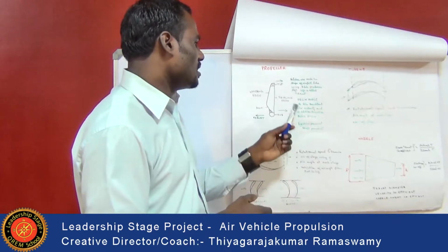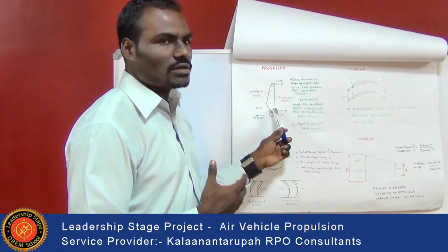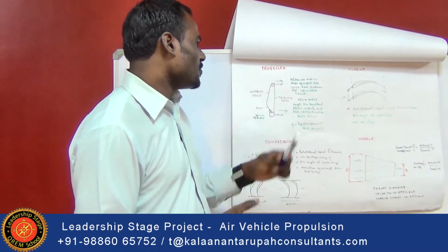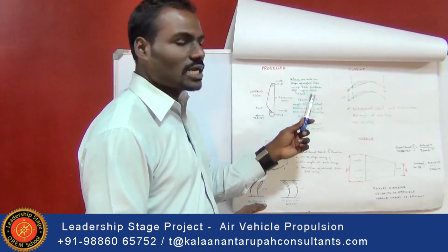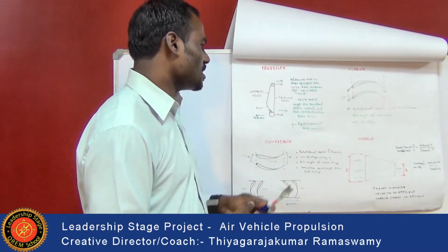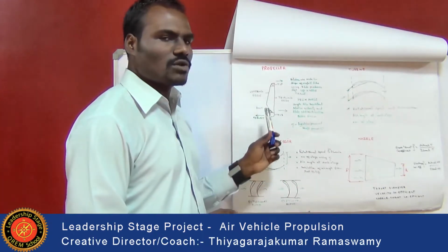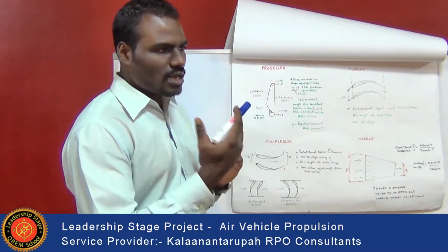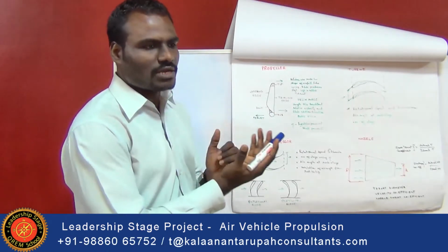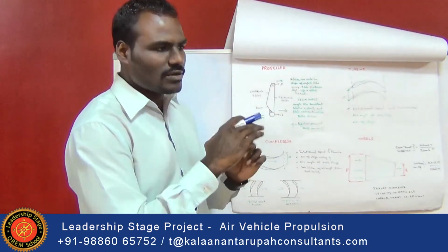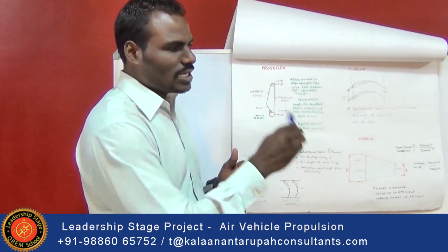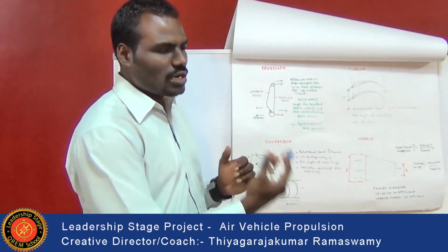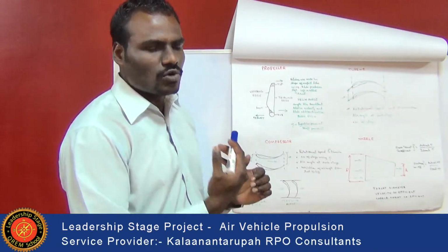So the main factors we are going to consider are the thickness and the diameter of the propeller shape. The blade produces a lift, which is nothing but the thrust that is being calculated, and the main factor we are going to calculate over the propeller is the helix angle. Here, the blades are designed in a way so that they form a helix angle with respect to another blade, so that the air being sucked inside the propeller should not move outside.